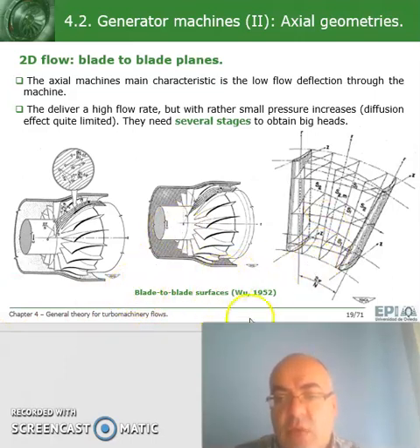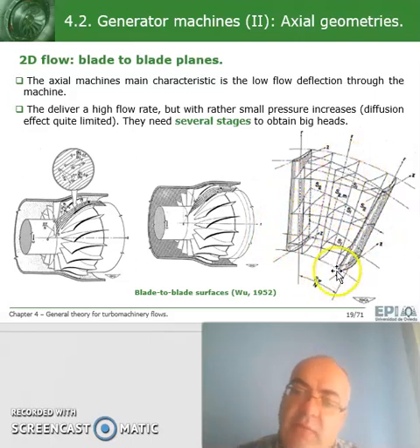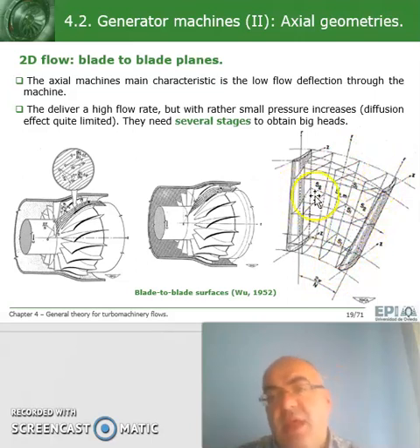For instance, who in 1952 did the division in the two main surfaces, S1 and S2, S2 here being the vertical planes more or less parallel to the blades, and S1 being horizontal or cylindrical surfaces for each radius, from hub to tip radius.